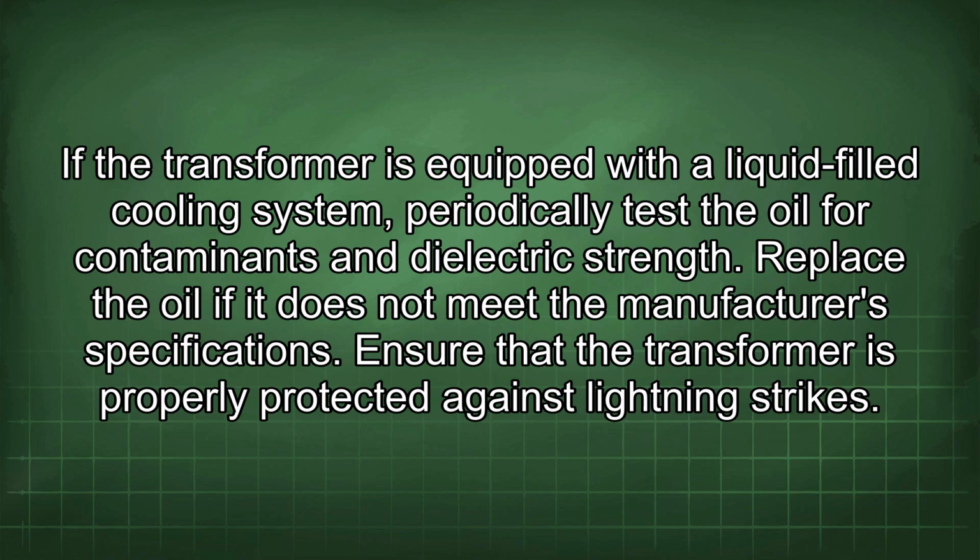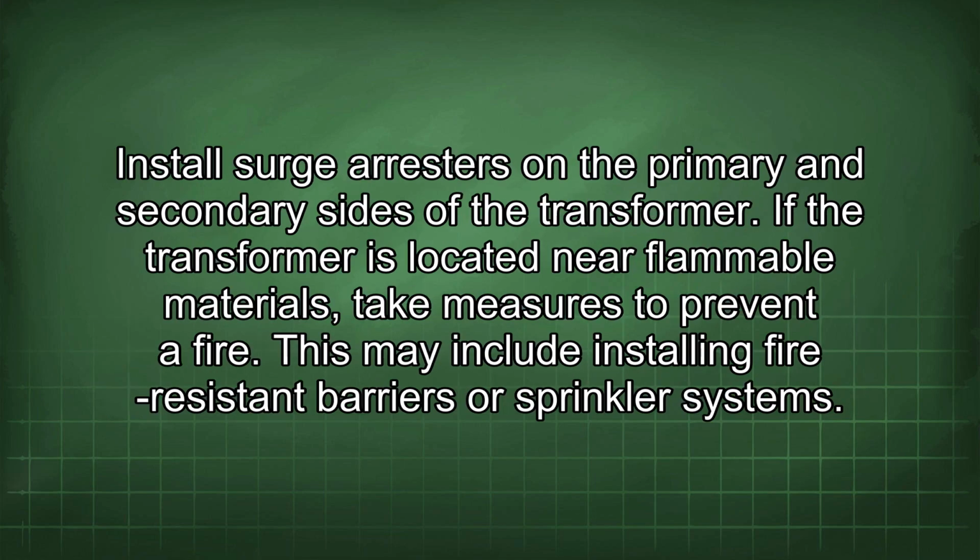Ensure that the transformer is properly protected against lightning strikes. Install surge arresters on the primary and secondary sides of the transformer. If the transformer is located near flammable materials, take measures to prevent a fire. This may include installing fire-resistant barriers or sprinkler systems.